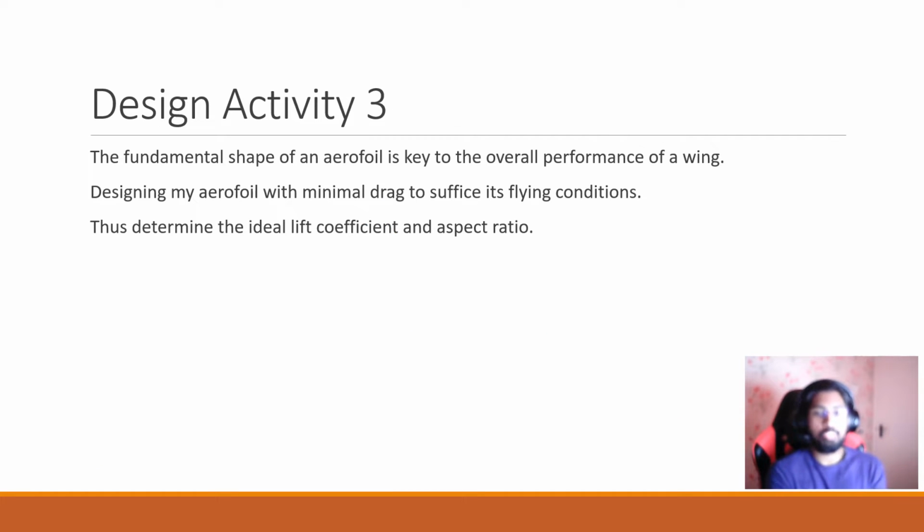In design activity 3, the fundamental shape of an airfoil is key to the overall performance of the wing. Its sensible design is therefore crucial to maximize the performance of the wing. Since the aircraft will be spending most of its time in cruise, the drag should be minimized as much as possible. It is this flight phase where I will be designing my aerofoil and wing.